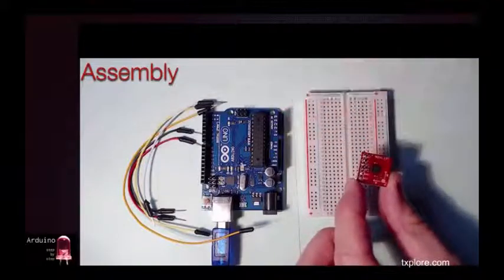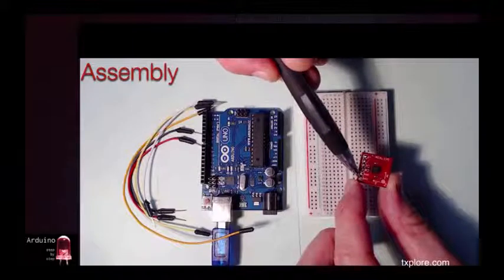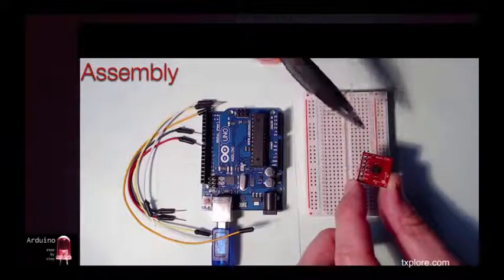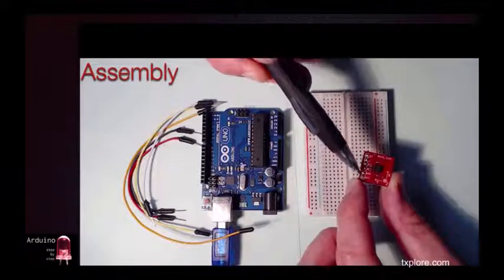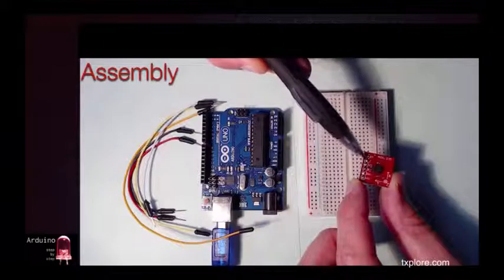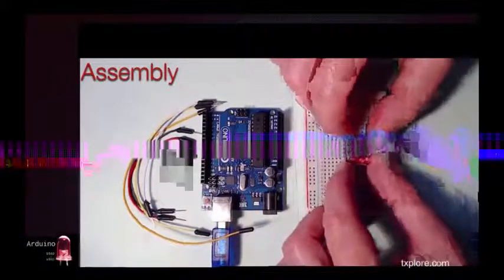Connecting this accelerometer to the Arduino is very easy. All you've got to do is to use 5 wires to connect the 5 pins from the device to Arduino's power, ground, and 3 analog input pins. So just plug it anywhere on the board.